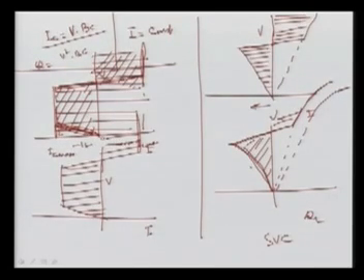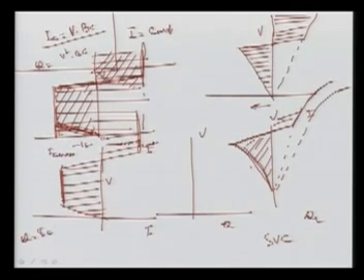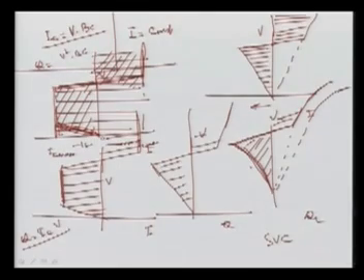Now if we go for the reactive power, I can draw it here. This is your Q, this is your V. This horizontal line, as I said, means Q will be your IC times the voltage. So it is linear. Now we can have this characteristic here, and this zone also we can have. You can see this is better: this value is very less, this is more reactive power support, and this is the characteristic of STATCOM.